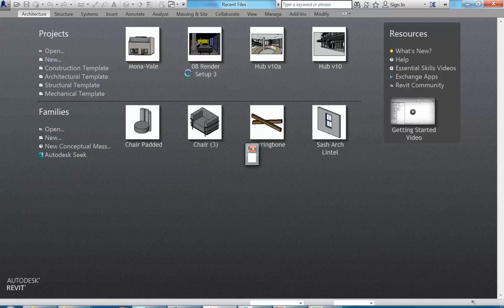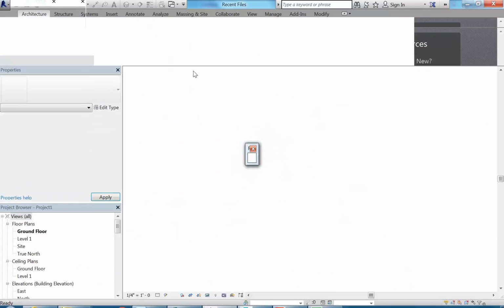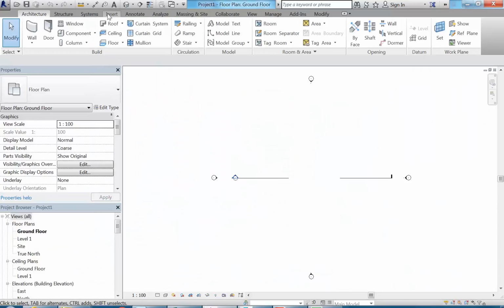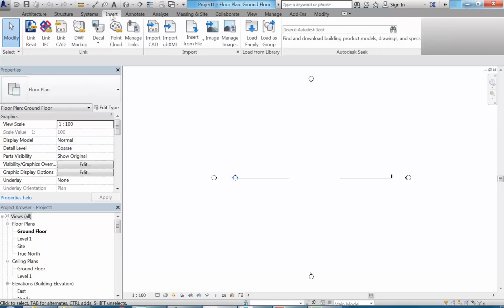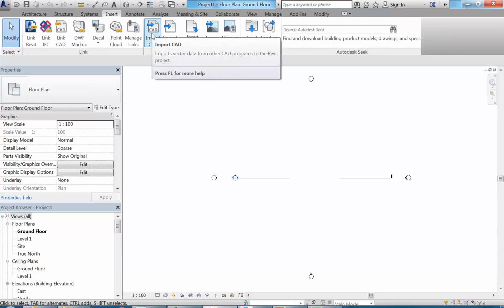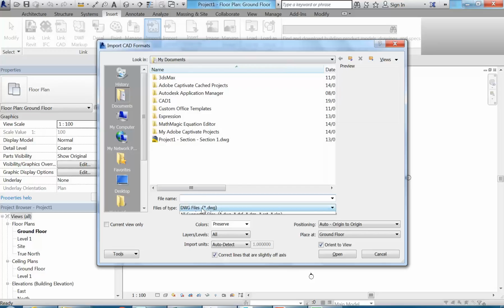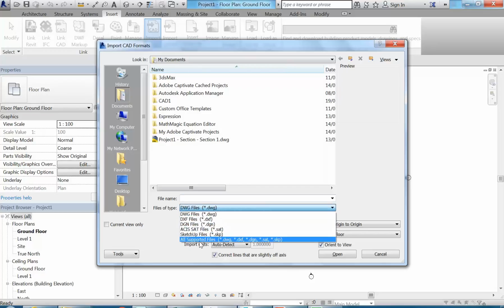And then you'll see, if you try to import a 3D model into Revit using Import CAD, you have a much more limited range of formats it can read. It can actually read SketchUp files, but don't rely on that, because when you bring a SketchUp file into Revit, it'll behave a little bit unpredictably.